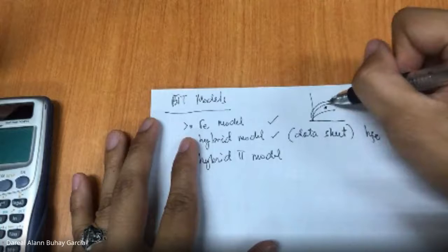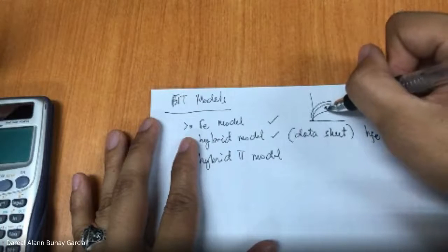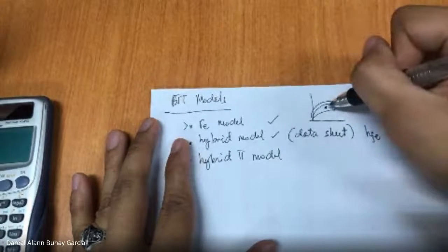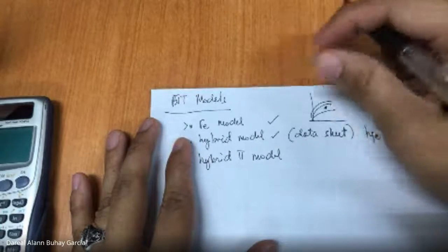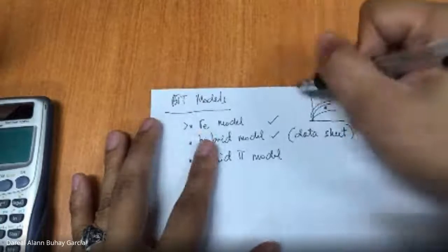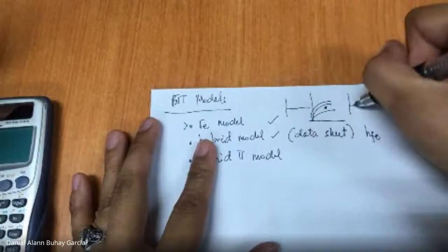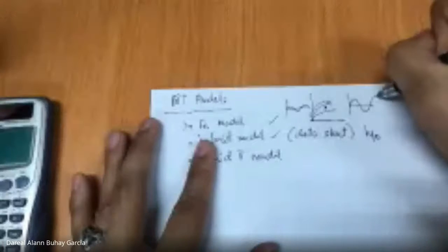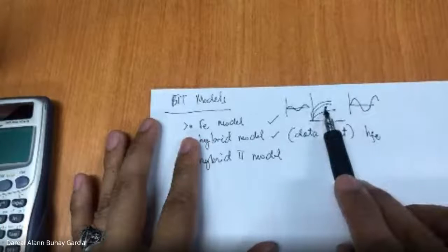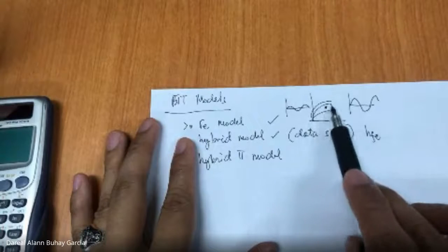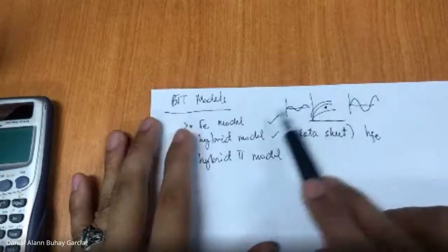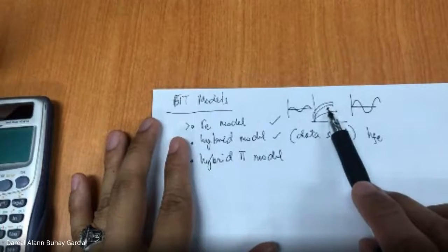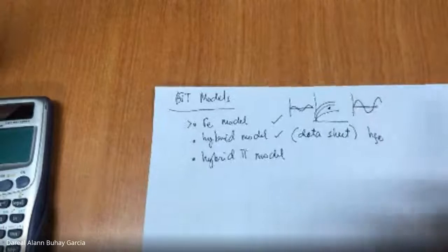If our input signal swings in value, it doesn't have a big effect. Our transistor operates linearly, so to speak, such that our output is an exact amplified recreation of the input. If it is not within this region, even if we design our BJT as an amplifier, there is a possibility that, if it is not in the middle, some values get clipped off. So we don't want that.